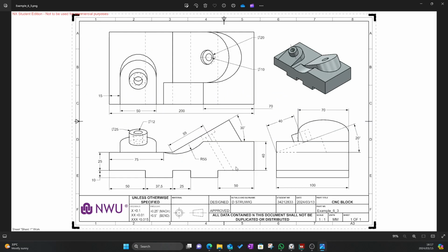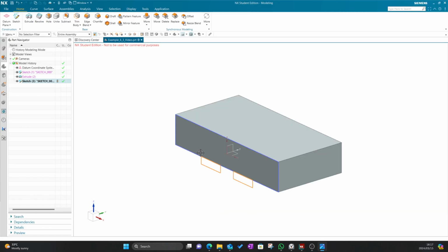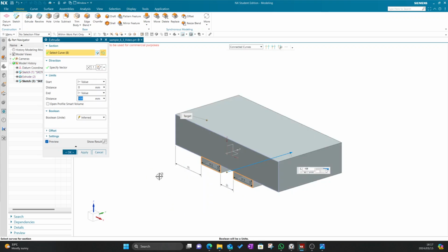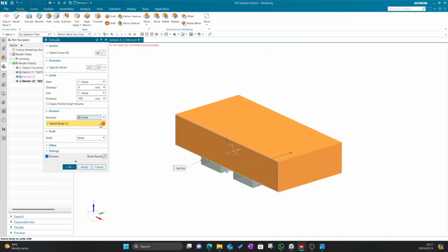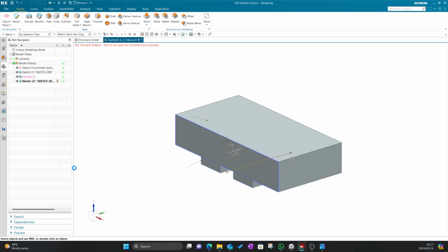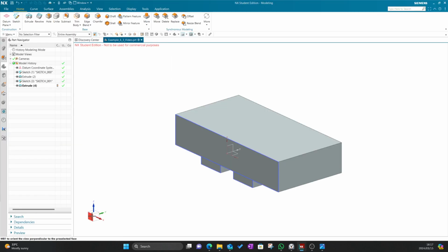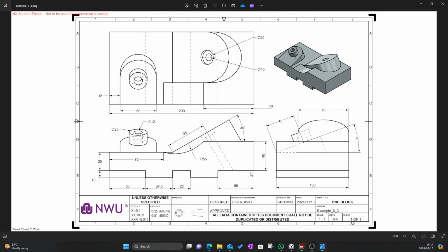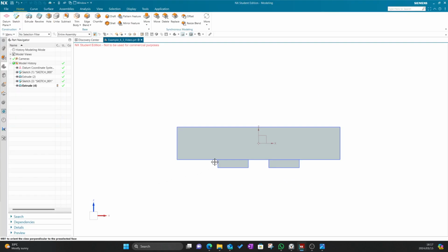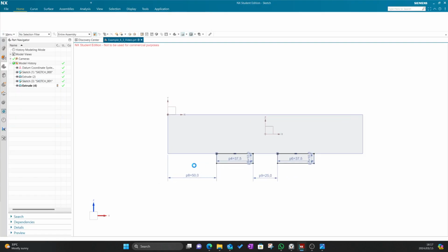I'm going to finish the sketch, and you'll see that they go right through. So it's that feature in the technical drawing. They're also 100 millimeters extruded. Just change the direction, and I'm going to use the unite Boolean operation, and it will unite those two steps to this main body. Click OK, and there we have both of those steps. If you look at the front, you'll see it looks quite similar to what we have there. I just want to make sure that that is 50.